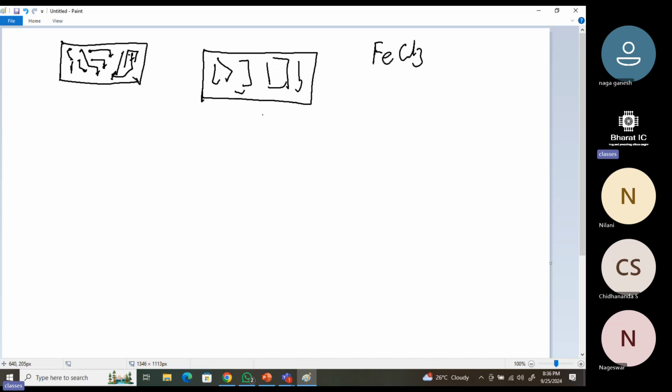The design is ink printed over paper, and that ink got transferred to the board. Wherever the ink material is, the copper is hidden and will not come into contact with the FeCl3. But wherever the copper is exposed, the FeCl3 will try to remove that copper.